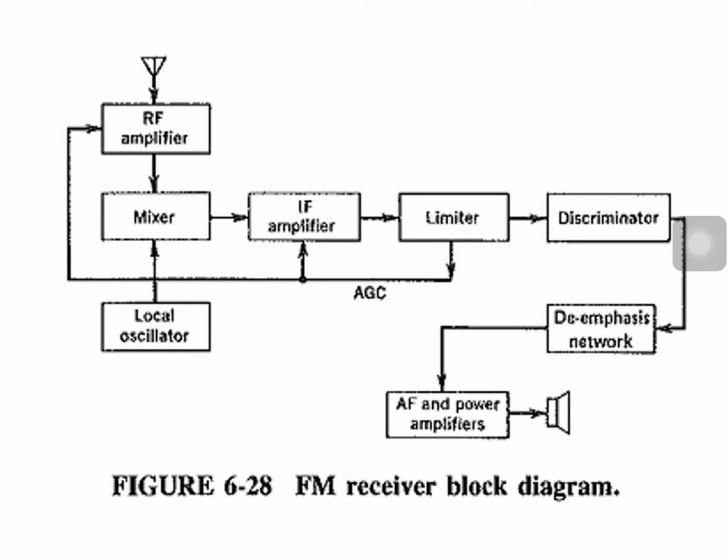And employing grounded gate, grounded base, and cascode amplifiers, it doesn't need neutralization. So for impedance matching of the antenna, this is the best option. And why doesn't it need neutralization? Because the input electrode is grounded in either type of amplifier, effectively isolating input from output.